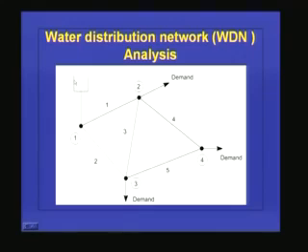So I will also tell you what the water level in the distribution reservoir is. Given the water level in the distribution reservoir, the demands, and the lengths and diameters of the pipelines, the question is what would be the piezometric head at node 3, node 4 and node 2, and what is the flow rate in pipe 4, pipe 3, pipe 1, pipe 2, etc. That means I have to find out the discharges in all the pipes and the pressures or piezometric heads